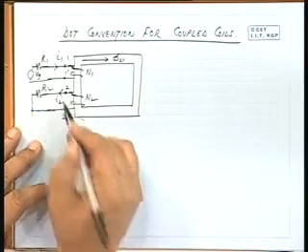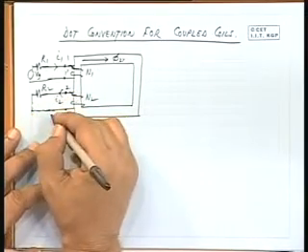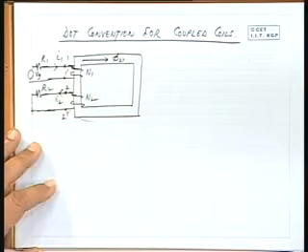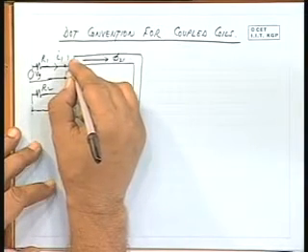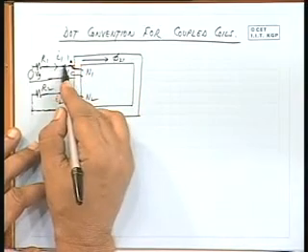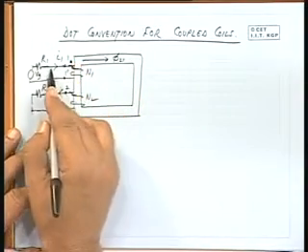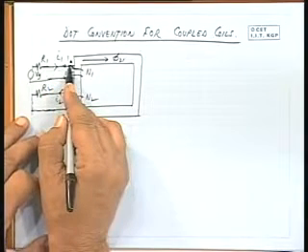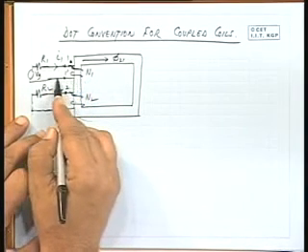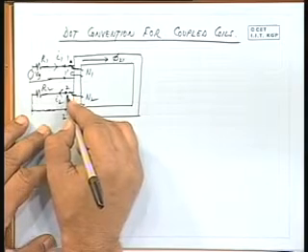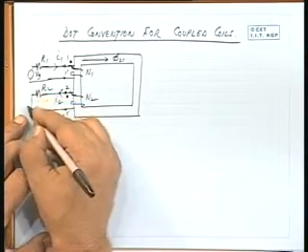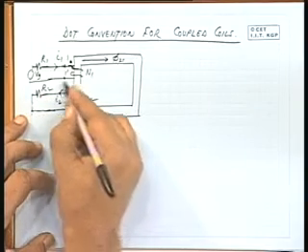Therefore, I will term this as a positive current when this is positive in coil 1. Okay. So if coil 1, this terminal is noted with a dot, that means current is entering from this terminal 1, leaving through 1 dashed, then in the secondary coil current is flowing from 2 and going to the external circuit from 2 to 2 dashed.